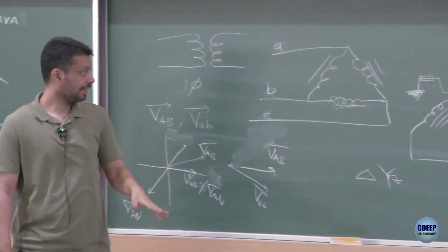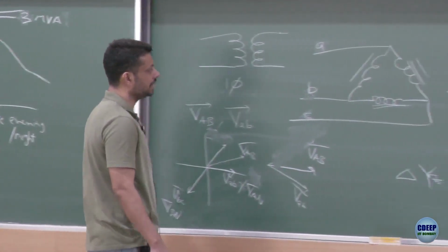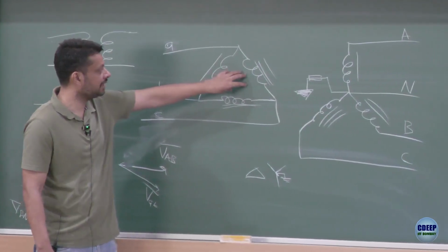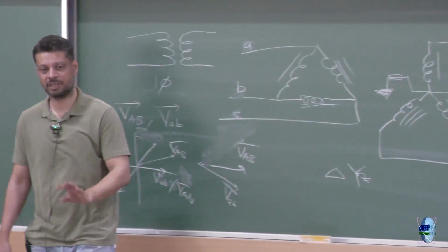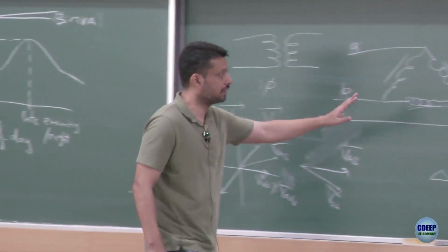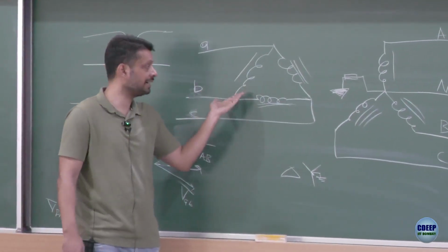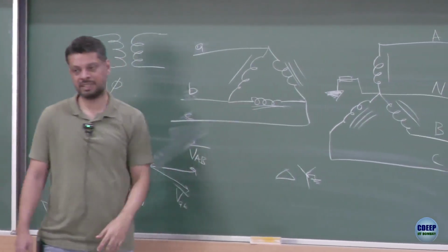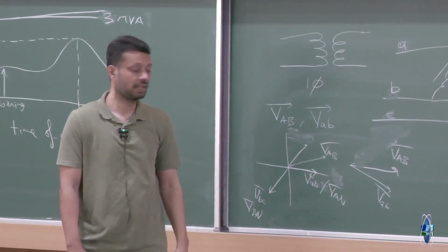The other thing, again my guess, is that it would probably have some implication on the material required to build this transformer, but that's something I have to check. I am not very sure. So the harmonics I am very sure about, that if you have third harmonic here, you don't have any third harmonic coming from the source, so that way it helps having a delta and a star this way. There may be extra benefits, let me just find out and then I'll update you in the next class.